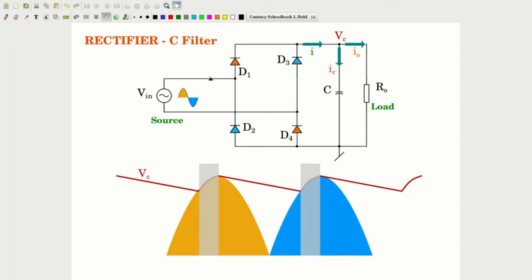a voltage source is seen connected to a capacitance. So there is a direct connection of two potential devices. So there will be a huge current rise here, and it is limited only by the track inductance, diode impedance, and any ESR of the capacitance and the inductances here. These kinds of non-idealities only will limit the current. So the current waveshape will be something like this. It will have a very sharp rise, and it will have a time constant based on only the series impedances coming in the path.